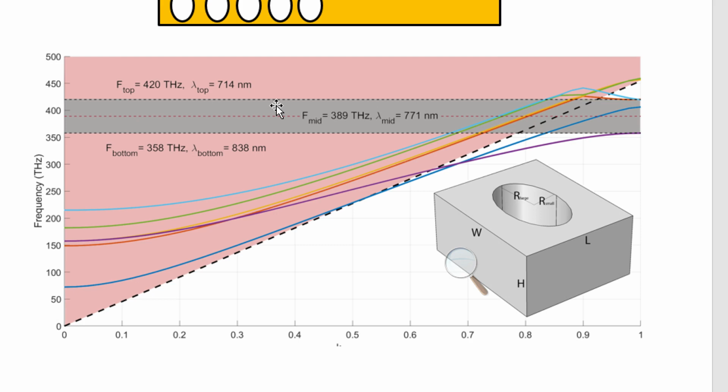The idea is that photonic crystal cavities confine the light, and we use this quasi band gap to confine a certain polarization, let's say TE. And if by any imperfection this TE couples to TM or scattering or whatever, that TM mode is free to propagate. So that would be the ultimate limit of Q in this photonic crystal cavity.